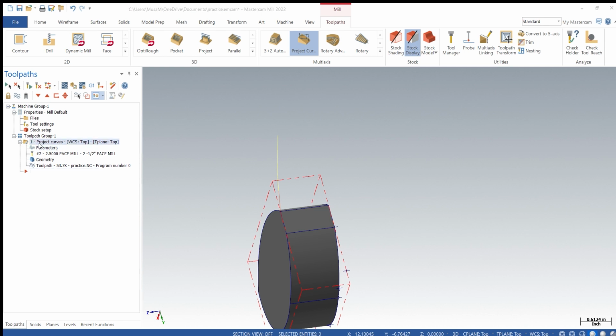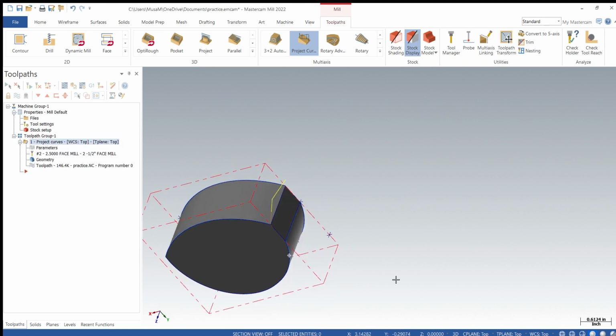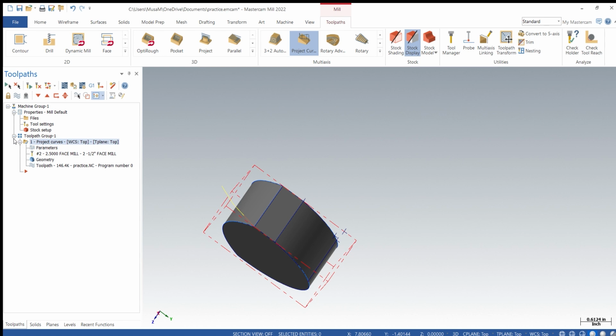But before we cover that part, we can also use some roughing settings, like going for 3 times with a little spacing, maybe 0.2, so it will have multiple cuts. And so we have half the part ready for the operation, so we can copy and paste it again.